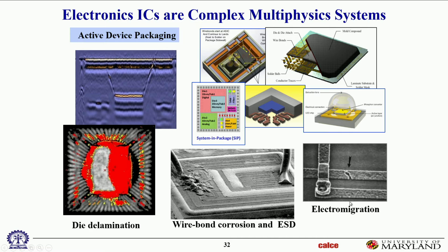So years and years of current density going through a product is going to eventually cause failures due to phenomena like those. So the whole idea is that you design your product to be robust enough. That means you design the metallization to be robust enough that it can survive 3 years of this kind of current density. Here's another example. These are wire bonds.